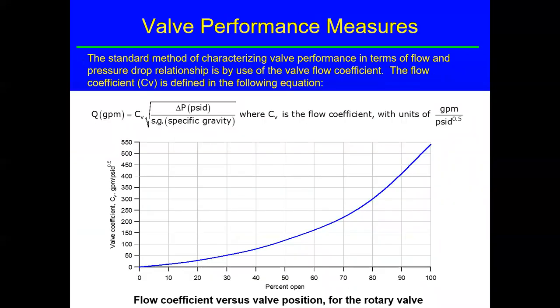Okay, so I sent you an assignment working with valve flow coefficients and working with those equations, which are much more detailed than this. This is the simplest version. It doesn't have the geometry correction factor or anything, so this equation as written, Q = Cv times the square root of delta P over specific gravity, would be for a system where the inlet, exit pipe and the valve were all the same size.